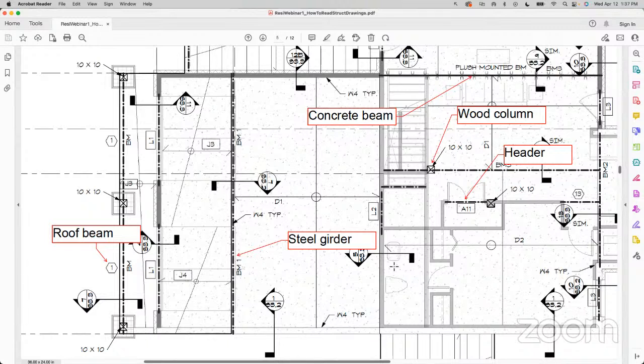So you'll see if you modify the center to center spacing in your deck joist calculator, maybe to 18 inches, just making up a number, then you'll see that deck beam that it's linked to is going to automatically recalculate because it's going to be a different PLF that's coming down. But that is a great question. Thank you.